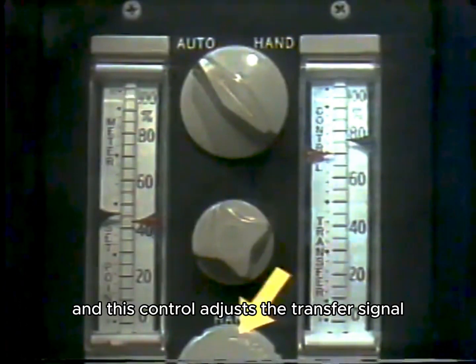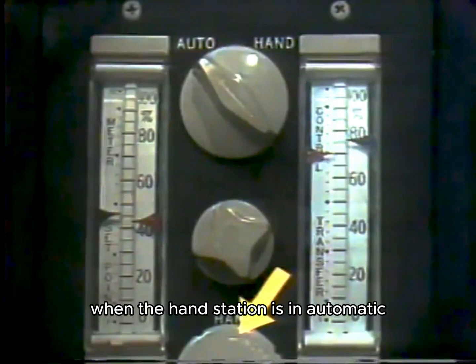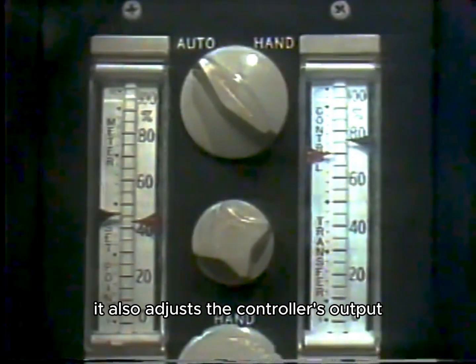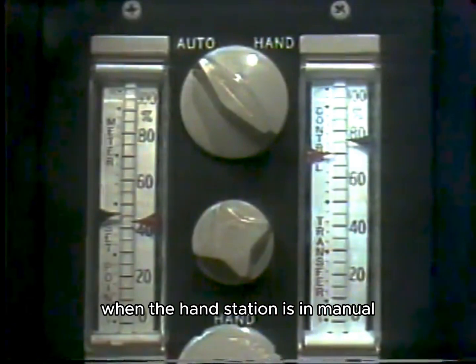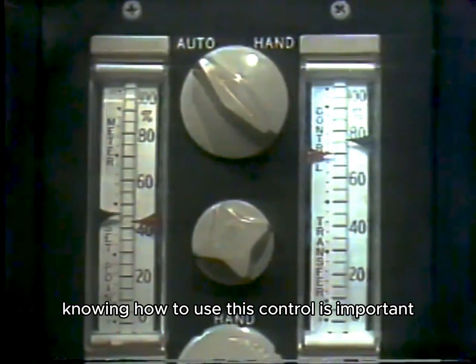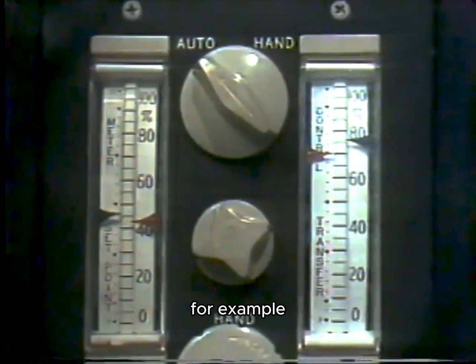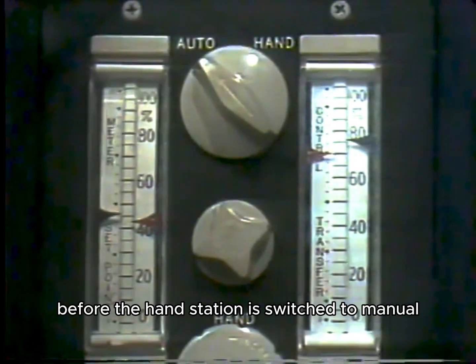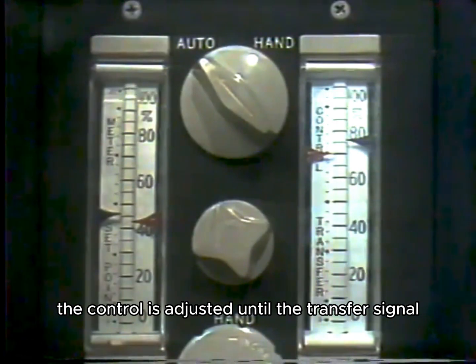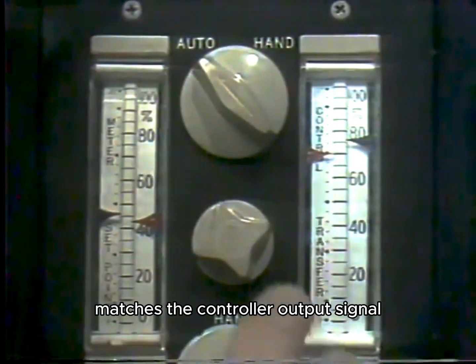And this control adjusts the transfer signal when the hand station is in automatic. It also adjusts the controller's output when the hand station is in manual, which means it's controlled by hand. Knowing how to use this control is important. For example, before the hand station is switched to manual, the control is adjusted until the transfer signal matches the controller output signal.